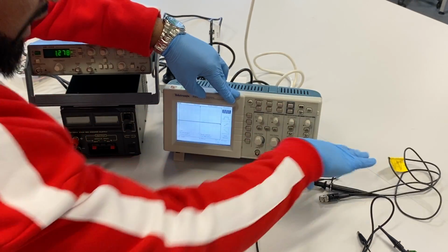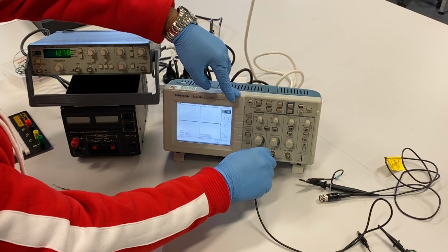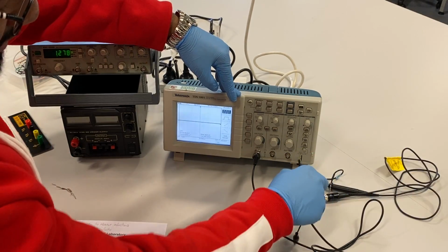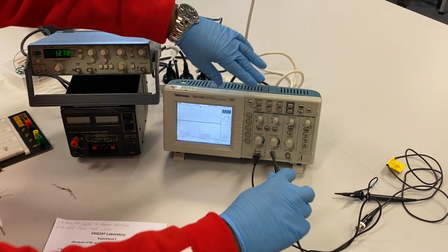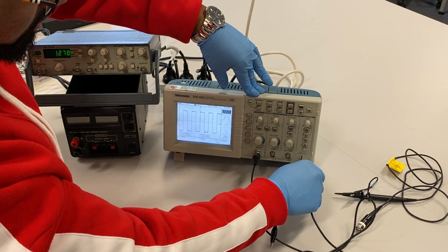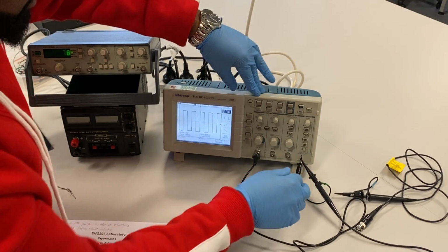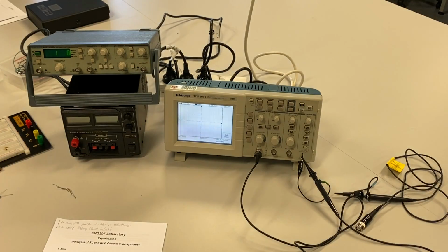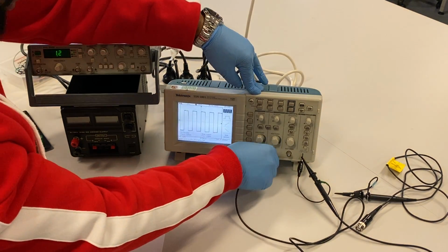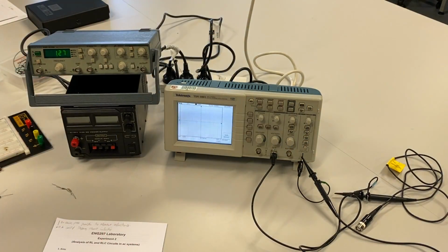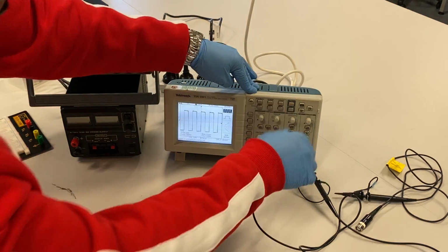One very good cable. We put another cable. You can use any channel to test, but I just want to test one by one so that there's no noise on the oscilloscope. So take this one, connect ground to ground and do the same, auto set. You see, the cable is working. If we use channel 2 to test if the cable is working and we get the same result after auto set again, it means the channels are fine, and the cables are fine.